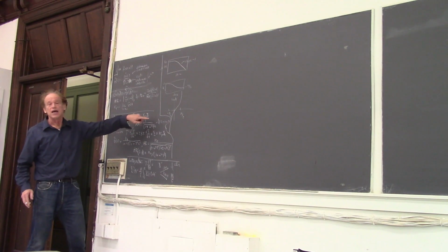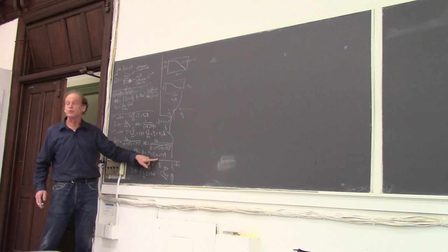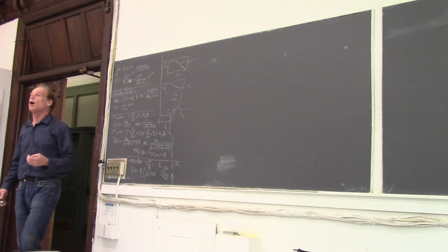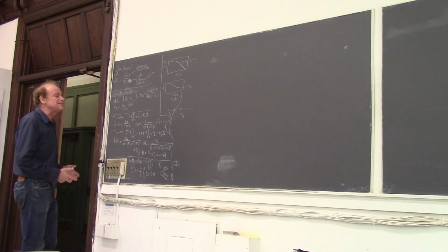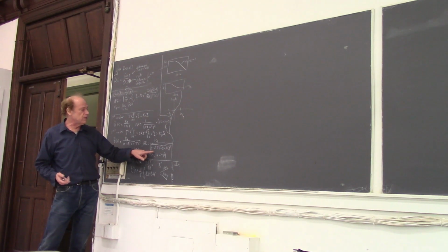If I take this and another one, and I multiply them, I'll get the square root squared, which is 1 plus omega squared t squared in the denominator. That's, of course, in the case where C is equal to 1, which corresponds to the case where I have two first order systems in series. If I let C be anything other than 1, it's a more general second-order system that's not just two first-order systems in series. But when it's two identical first-order systems in series, then C is equal to 1, and then I just get this expression right here.